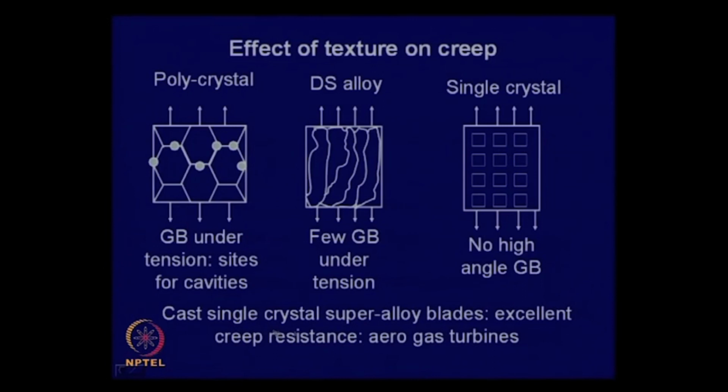In fact, cast single crystal superalloy blades have excellent creep resistance, and they are used in many aero gas turbines, and even new generation land based power turbines are potential applications for these materials.